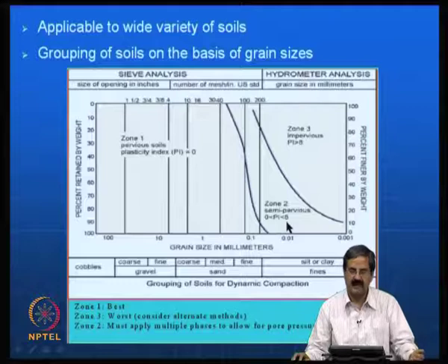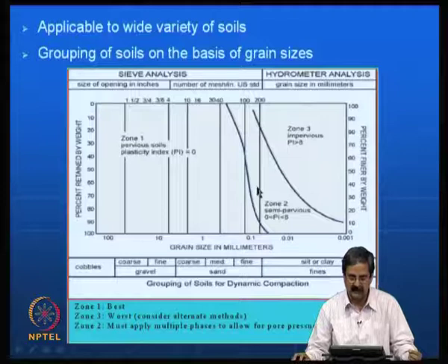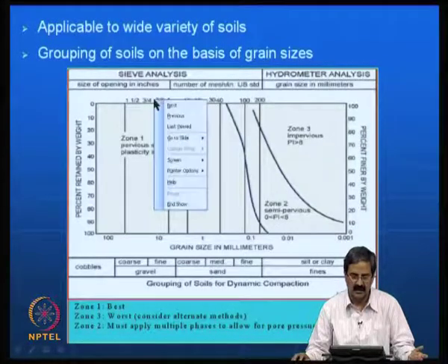In the case of sands it can be a little rapid because you are depending on pore pressure dissipation, but here the grain size being a little smaller, you need to look for delayed time intervals, or another way of improving pore pressure dissipation. So essentially one can improve many types of soils using dynamic compaction.